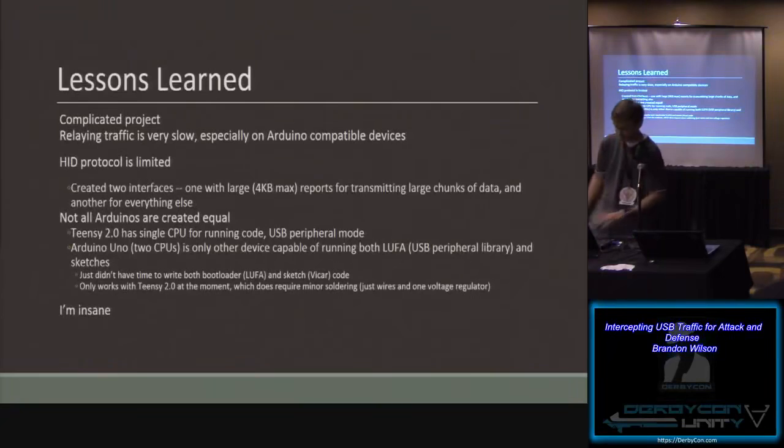So wrapping up, this is definitely a complicated project to try to accomplish within the few weeks I gave myself to work on it. I had to completely rewrite the USB host shield library for the Teensy so that I could create the protocol and the interface for manipulating USB at a fairly low level from a PC, working from the ground up and trying to build a relationship between the USB host shield's chip and a libUSB-like interface on the PC. Also, relaying traffic like this is really slow, so to accommodate that, I modified that .NET DiscUtils library to add a caching layer, so it would only read sectors from the drive as it needed them to interpret the FAT32 partition, and come up with a way to communicate overhead and send large chunks of data as quickly as possible.